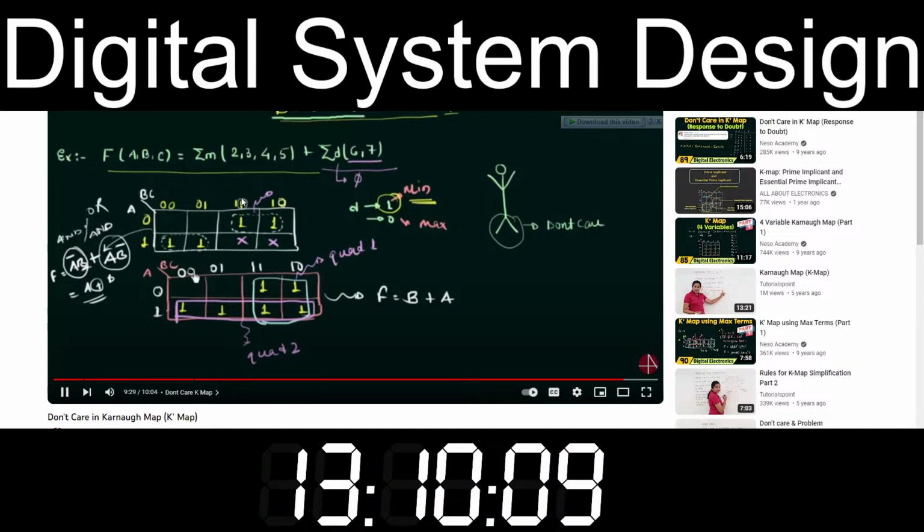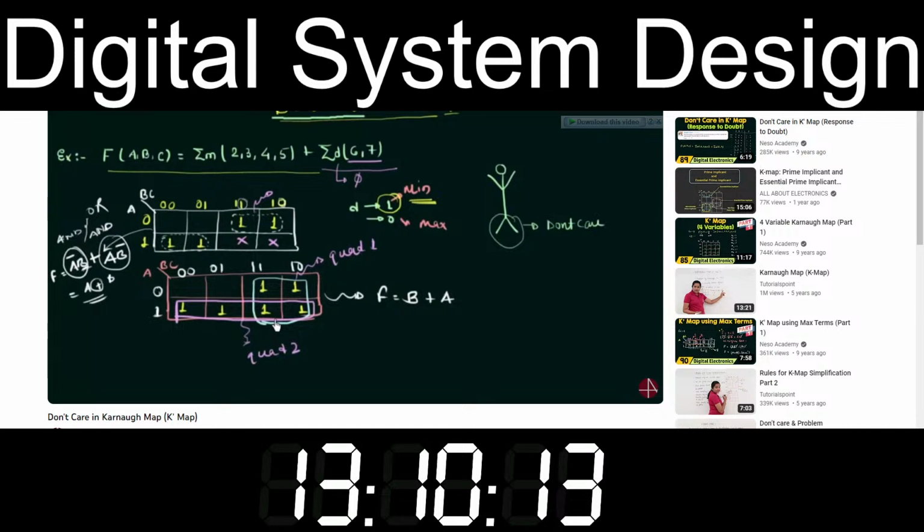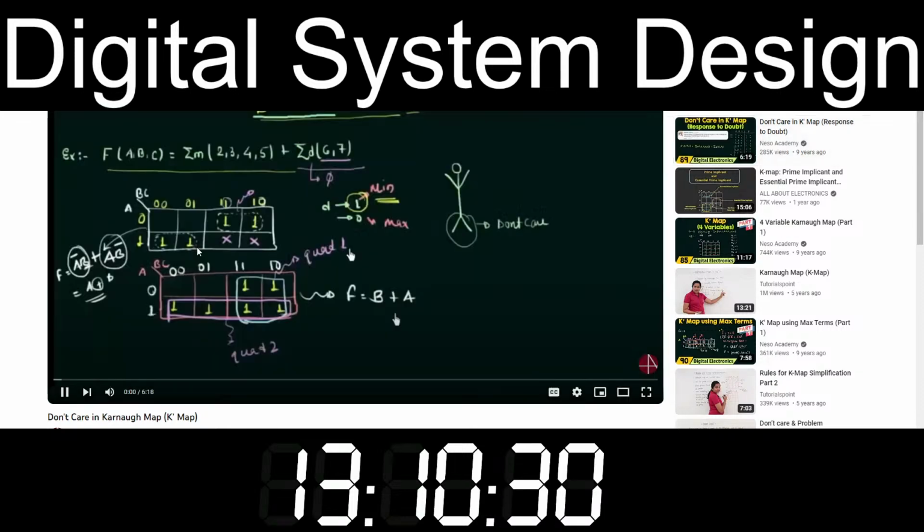So 3 gates are required, but here only a single 2-input OR gate is required. So this is the advantage of using the don't care as 1 in case of min term grouping, and 0 in case of max term grouping. So I think it is now clear to you what the don't care is and how we have to use it.